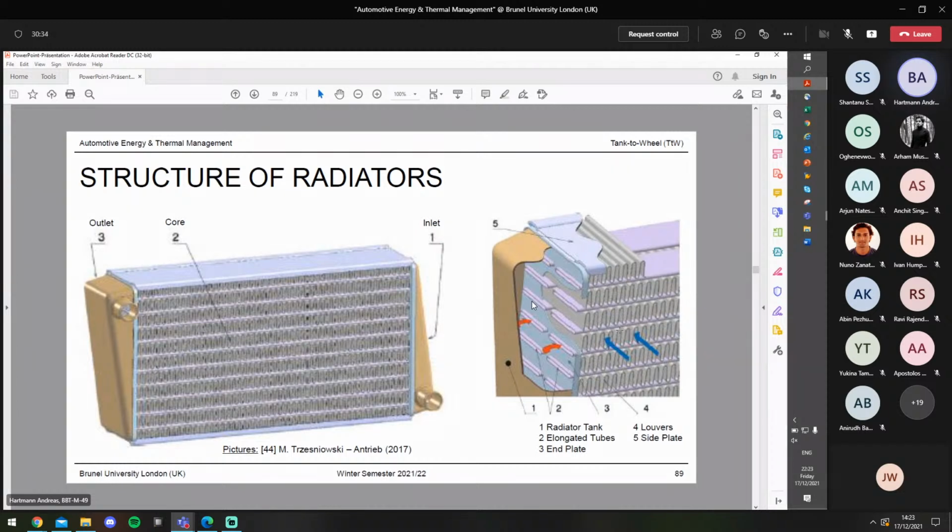There you can see on this picture, there are many small fins established in such a radiator, and therefore the surface which is touched by the airflow is approximately 50 times higher than the projected surface. So this would be the projected surface, but if you then use many fins like shown on this detailed picture here, then you can dramatically increase it.